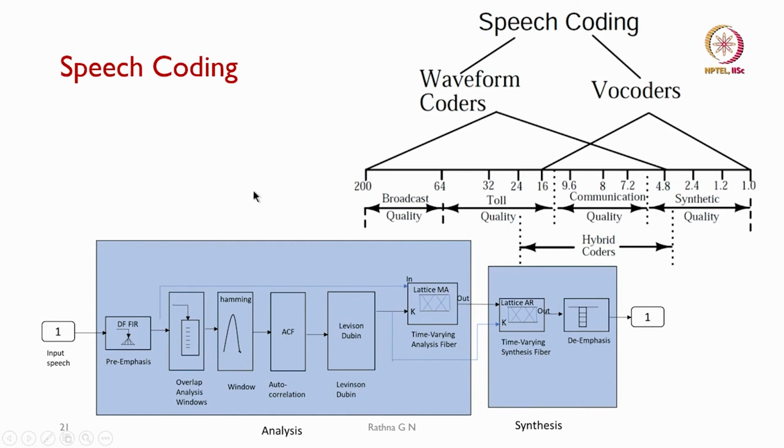Next we went on to discuss speech coding techniques, whether we had waveform coders or vocoders, what kind of applications they are used in, and which bands they are going to be used in. One example we took was one of the students' projects to show how LPC coding can be done, both analysis and synthesis, and then reconstruct your voice at the receiving end, almost equivalent, we will not say the same, but at least it is going to match with whatever voice was getting generated.